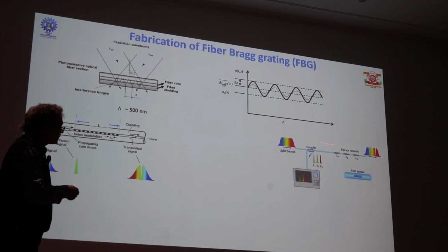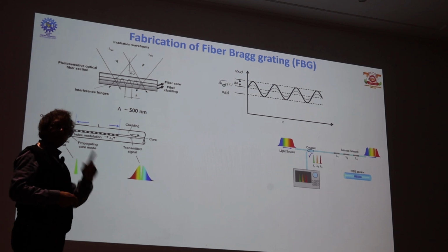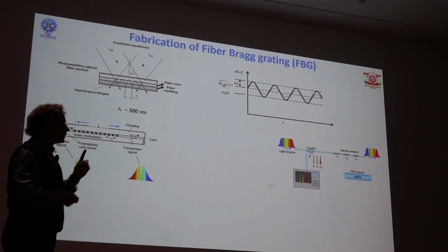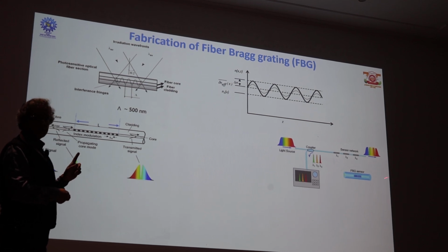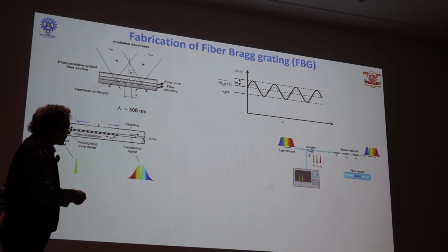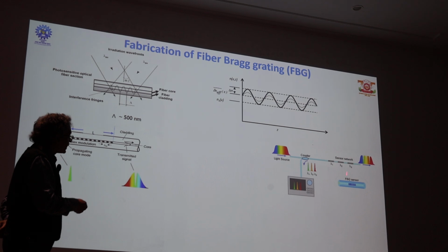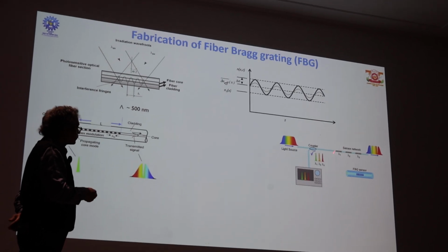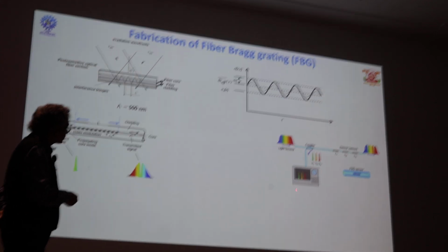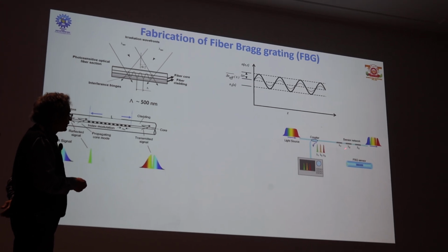So this is nothing but the multiplexing ability of a particular device, where through the same signal carrying system I am getting information from different centers which is wavelength coded. So in the control room or on the detector side, I know that there are 3 Bragg gratings and where they are situated, and I know also how they are wavelength coded. So if I am able to get this signal back, I am able to track this particular structure in terms of its wavelength.